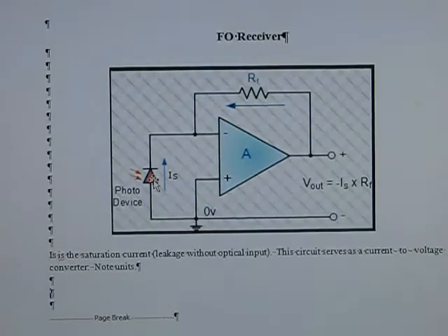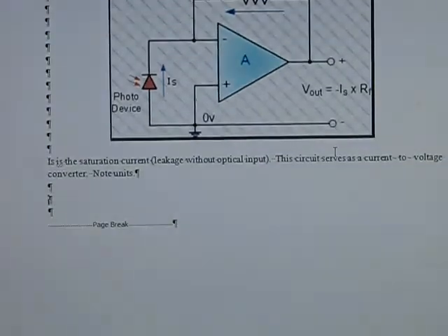So this current is being generated totally by photocurrent and a function of saturation current. The current then flows through RF, and we see the output at V out, which would be a relatively low impedance source. And then if we needed to, we could amp it up and convert it into a digital voltage or whatever we need to satisfy our end purposes.